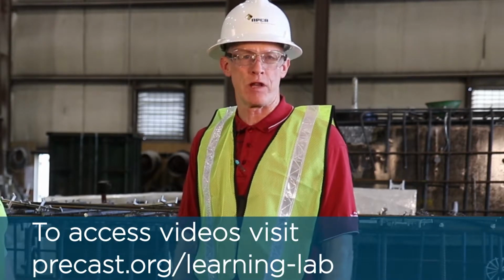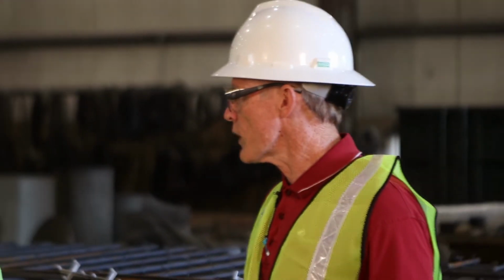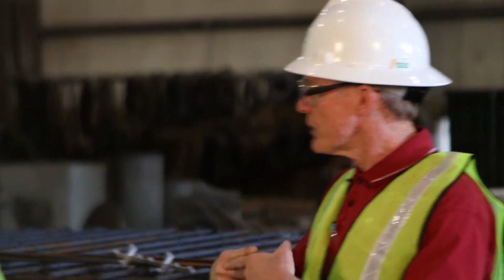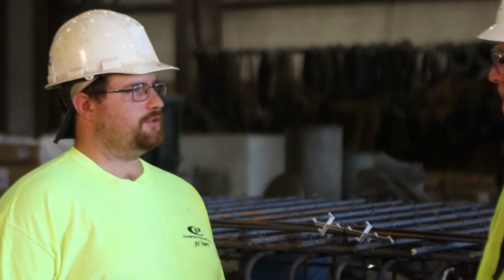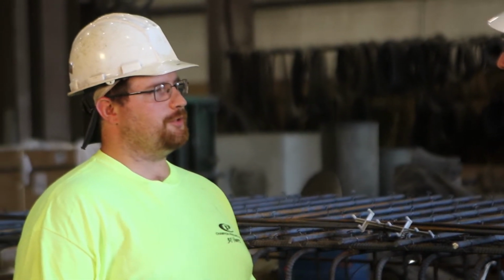Again, I suggest looking at the NPCA Learning Lab video, Reinforcement Inspection. It describes how to measure concrete cover to your reinforcing steel. It should never be less than 1/2 inch or what is shown in your project details and specification. So Michael, why don't we talk about how you conduct your overlaps and actually tie them together? Sure. So when it comes to splices, you can use one of two methods.